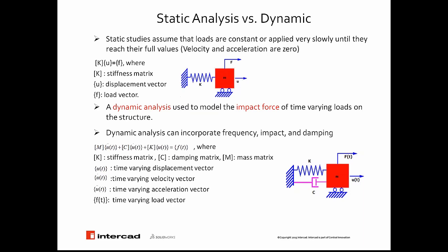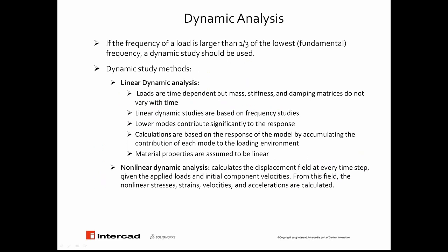Now from this point, we can have a second split. We are considering whether the K values or C values are time dependent or not. Let's move to the next slide, and this is exactly where we define different types of dynamic studies: linear dynamic studies and nonlinear dynamic studies. But one thing prior to that, when we are applying a dynamic analysis, the main rule is if the frequency of a load is larger than one third of the lowest or fundamental frequency of a system, a dynamic study needs to be applied.